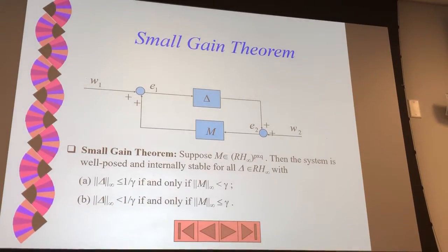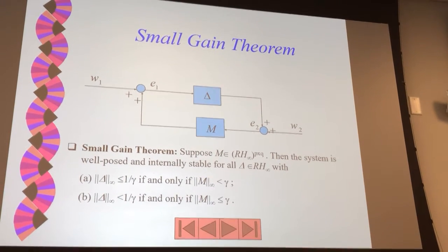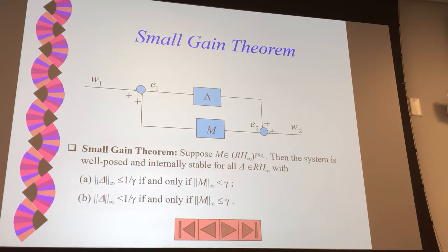So in this case, M is known, because this is based on the nominal model and your design K. Then I have W here. So this is the small gain theorem. Then we can use this to check how big my uncertainty bound could be. That's very important.